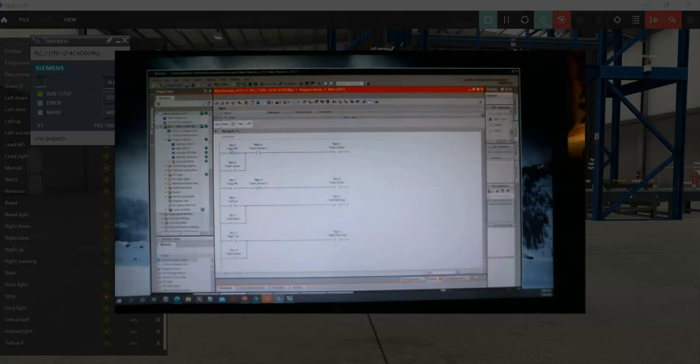Now that's going to show you which ones are on and which ones are off, and pretty much everything is off to start with. And by the way, I should say we also use a startup block here. And this startup block is because the Siemens PLCs maintain the output even when you're changing the program. So if you go offline to make a little change to the program and then go back online, the outputs will still be in the same condition that they were.